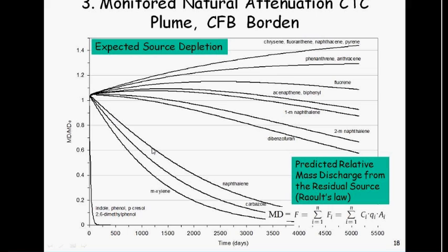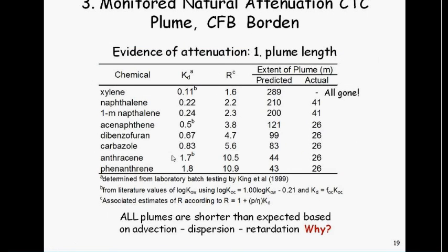Yes, the cumulative mass in the plume, if this was the only process, would be going up. But if a mass removal process can remove a certain mass discharge, and you now drop below that input, then you should see the plume mass go down. That would be the rationale.